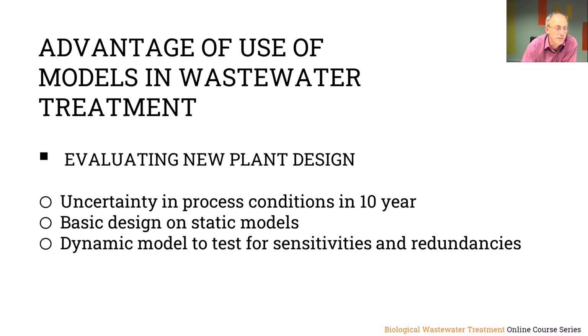But you can use a dynamic model very well for testing for sensitivities, what is sensitive in your design, and for redundancies. Typically, in most of the static design protocols which are available in practice, there's a lot of safety factors. Because if you have a standardized protocol for designing a wastewater treatment plant, like in Germany, then that design has to be made for the worst treatment plant in Germany, because all treatment plants should work well, even the one in the worst condition.